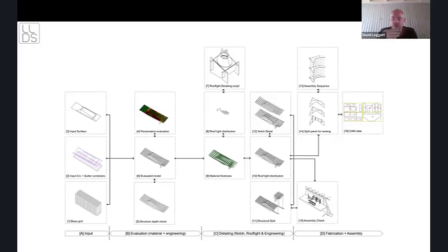And then through the scripting, all the components that we had to CNC fabricate would naturally get adjusted on their nested sheets. And so it became a really efficient way, if there was that last minute change, to just press a few buttons, regenerate the form, and we had new files to CNC mill.